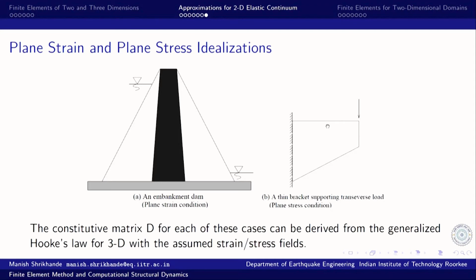Out of the plane it is completely stress free, and since the thickness is small, the state is not going to change much across that thickness. So, this problem is idealized as a plane stress problem, and again we consider the stress distributions in the xy plane,